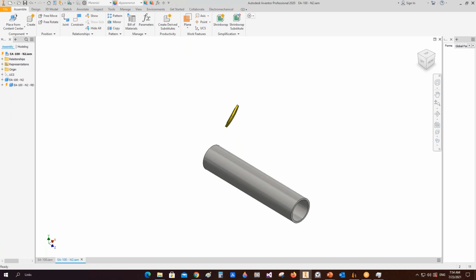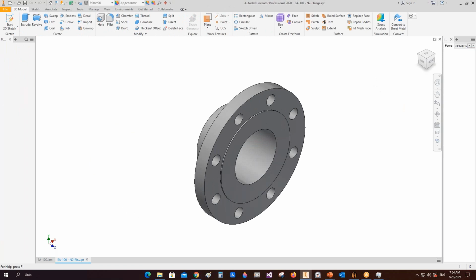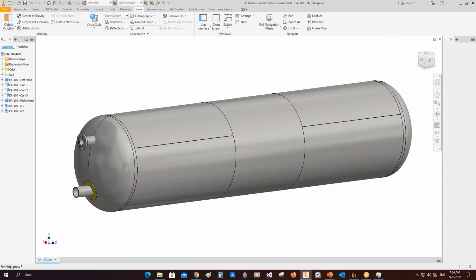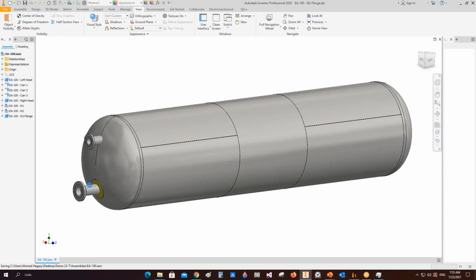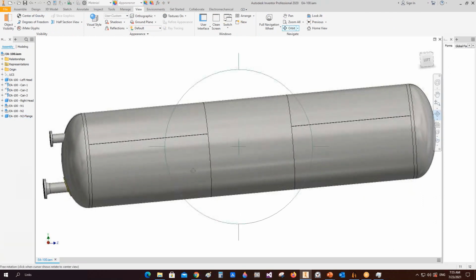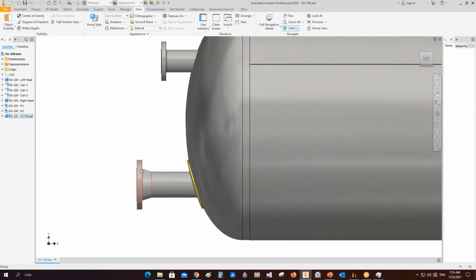You can figure that we have built now updated, so updated and assembled with the nozzle. After that, it will be assembled to the final assembly of the vessel. The same for the flange. Now the flange is connected to the end of the nozzle. Now we need to control the projection of this nozzle. We need to make this projection look like the top one.